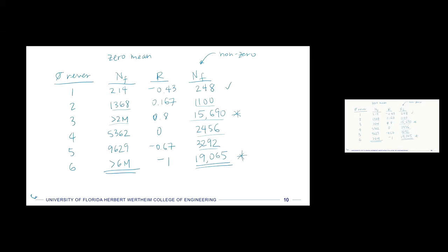So you can see now that if we account for the non-zero mean stresses or mean strains, we get quite a significant difference. And in this case, a drop in our allowable life, at least for these ones here. But we actually got an increase in life for the first one. So if we add all of that up, we do 1 divided by those for the non-zero case, right? We get 1.038, and this one was 1.025. Okay, so it's really not that much different in this case because we got a longer life for that first cycle, but shorter life for all the other ones. The ones that we got shorter life for have lower stresses in general, so it's sort of balanced out in this case. I would not expect that to happen for most cases. So we got values of greater than 1 for both of these, which means that we could actually reduce the size that we chose ever so slightly and then reiterate through.